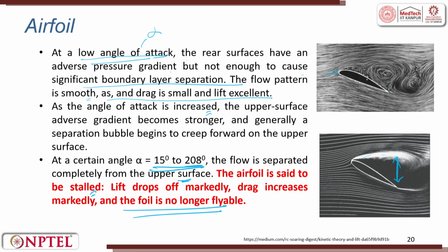Okay. So, this is what they are trying to talk about. You see a vortex getting created, then when the angle of attack is increasing, the upper surface adverse gradient becomes stronger and generally a separation bubble happens.